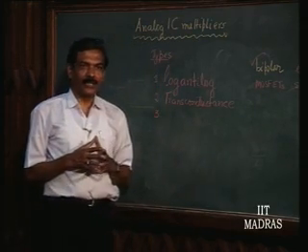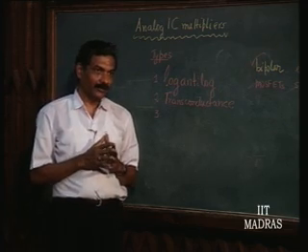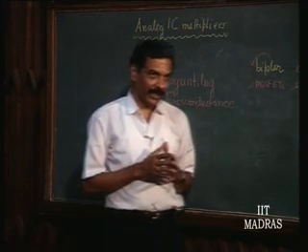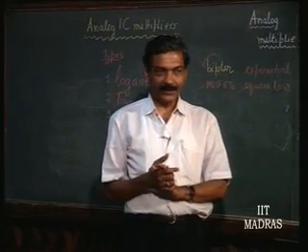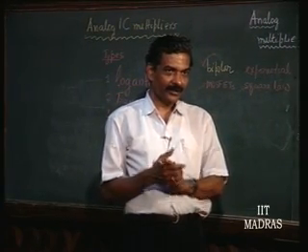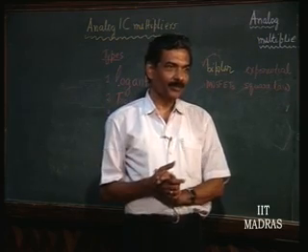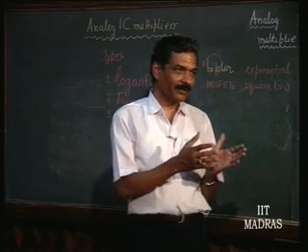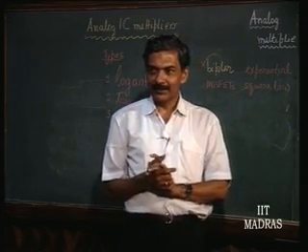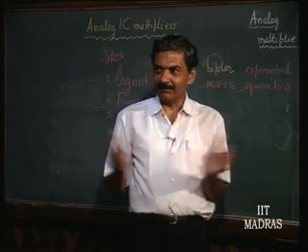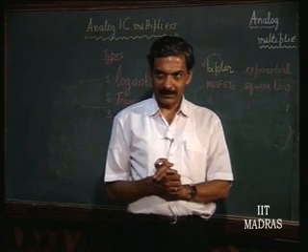The third one, on the other hand, is the basic principle that we had again learnt, that when I have a switch which can connect Vx or disconnect Vx, or connect Vx or connect minus Vx for respectively tau and T minus tau, I can get an average which is Vx tau by T. This we have discussed in switched mode regulators, power supplies.